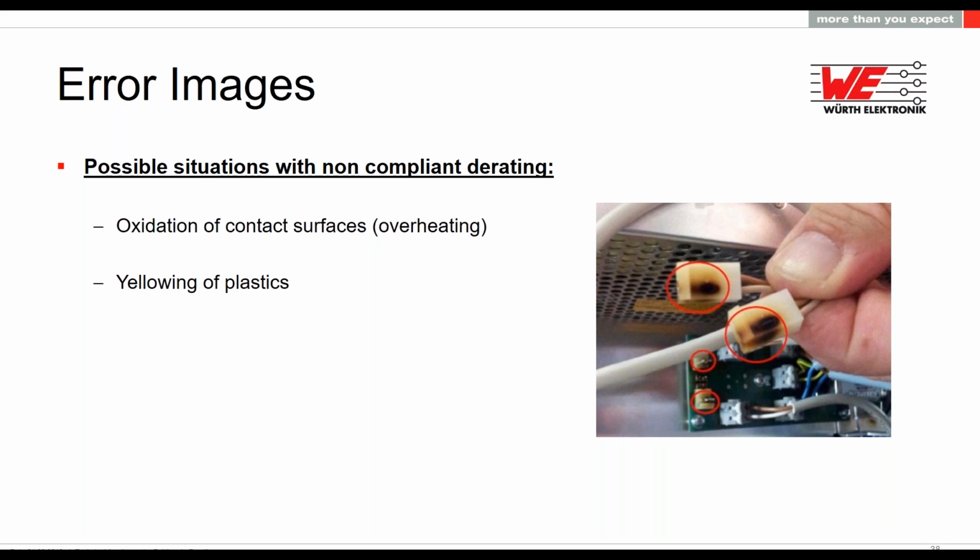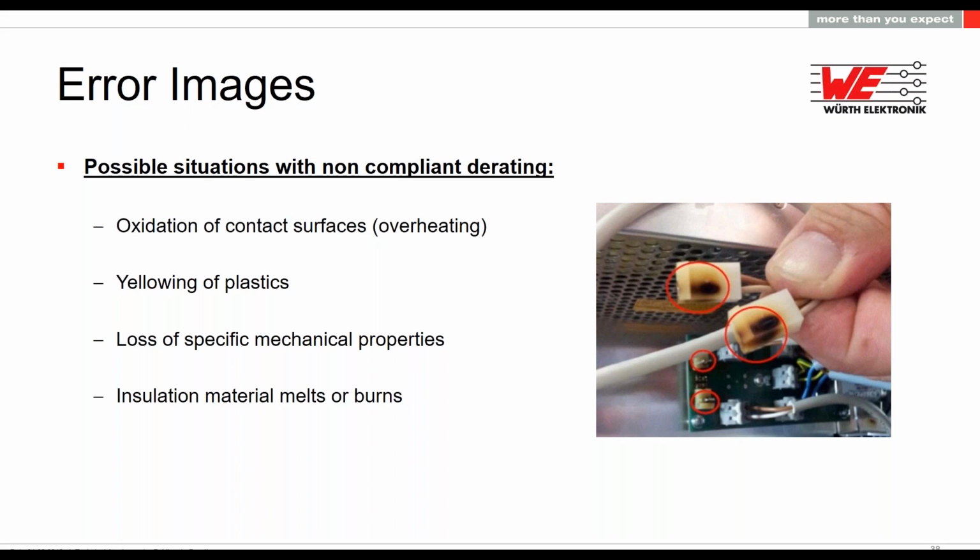In the best case, you see it before, you have decoloring, yellowing of plastics, but you can also lose mechanical properties if the plastic gets weak. Latches do not have the force anymore they should have, or they break easily because the plastic changes its behavior because of the temperature. It's getting more rigid. And in the worst case, of course, insulation material can melt or burn, and you have a complete failure of your component or even the whole application.